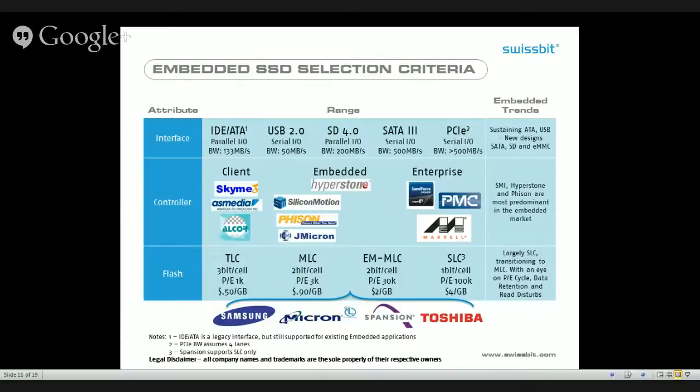When you look at all of this information in total, it's very important to select the right interface and select an SSD controller supplier that's going to provide you the best solution for your application. It's really important to look at all aspects of that selection. In the embedded trends on the flash piece, it's largely SLC, but there is a lot of transition going on to MLC. But with MLC, there are challenges in terms of PE cycles, data retention, and read disturbs, as I mentioned.